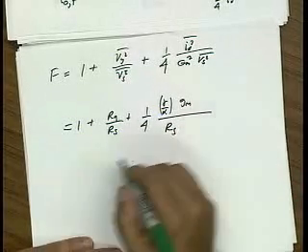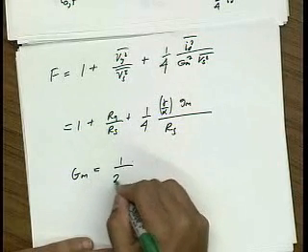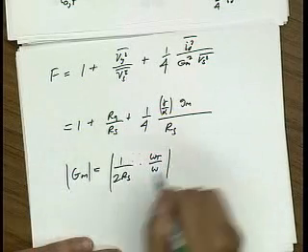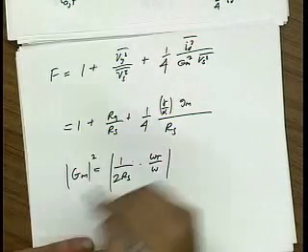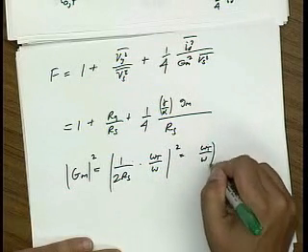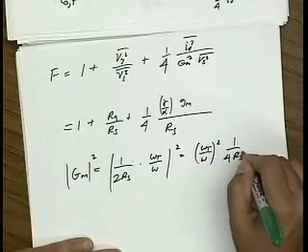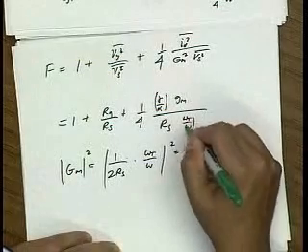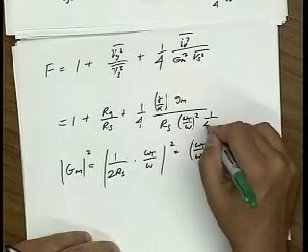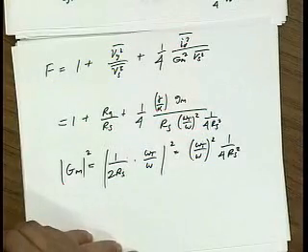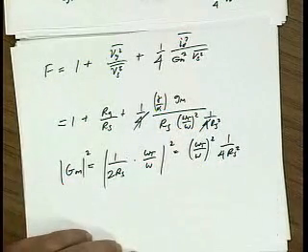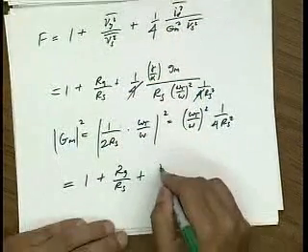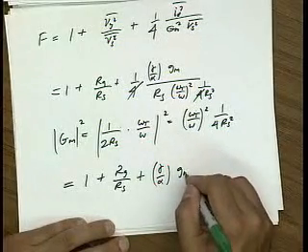And for gm, recall that gm is 1 over 2 Rs times omega t over omega. So if I square gm, I get omega t over omega squared, 1 over 4 Rs squared. So here I substitute, and guess what? This 4 cancels out with this 4, and I end up with the same exact expression as for the undegenerated MOS amplifier.